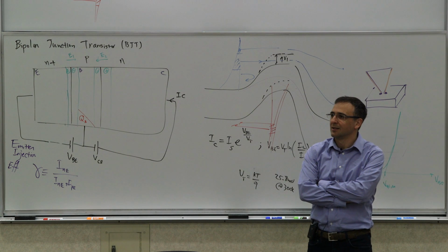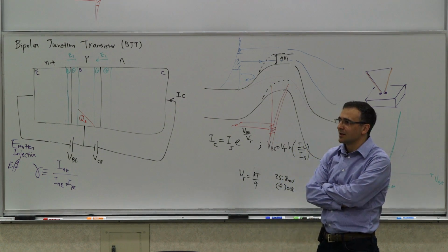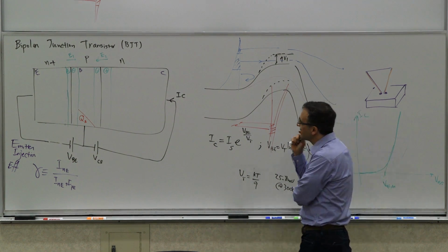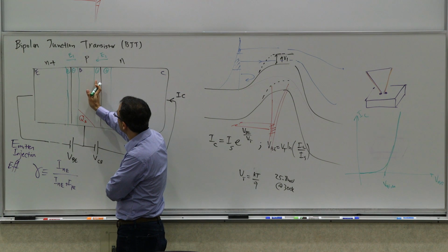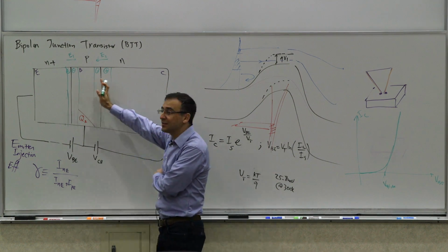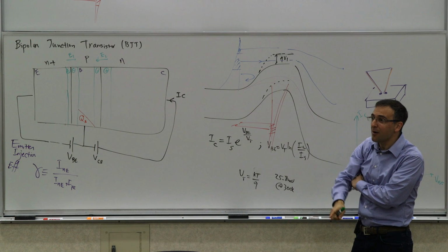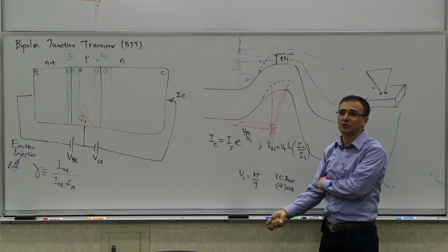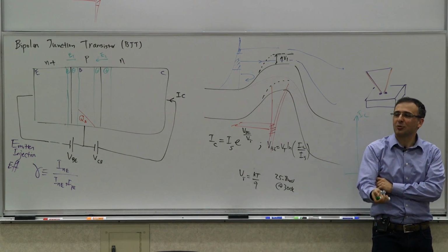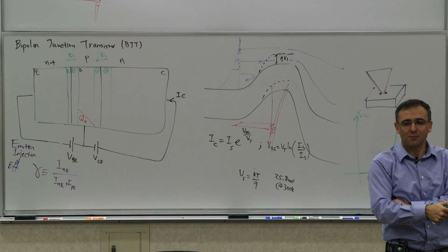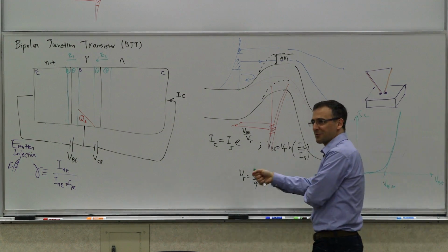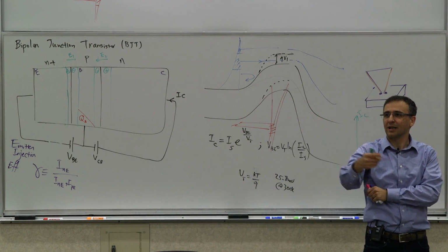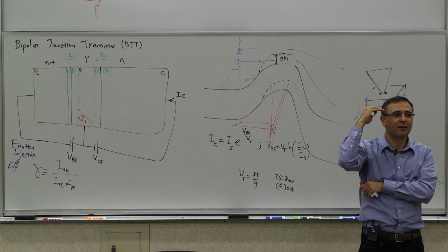Yes? If you lower the doping on the inside to get the depletion just almost touch, you get rid of most of the holes. So the suggestion is interesting. He says, if you lower the doping concentration on this side, then you can get these to touch, and then you will get rid of it, which is okay for the problem we are trying to solve, but it actually introduces a bigger problem, which is the lowering of this potential barrier, and you lose control. So it's a first order problem causing a zeroth order problem. But no, it's good thinking. I like it. Let's continue.